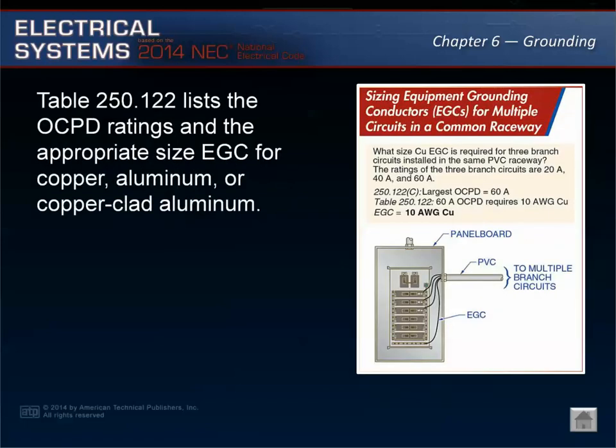The equipment grounding conductors shall be run in parallel when conductors are run in parallel in multiple raceways or cables per 310.10(H). Each of the equipment grounding conductors shall be a full-size conductor based on the ampere rating of the overcurrent protective device protecting the circuit conductors. See Article 250.122(F).